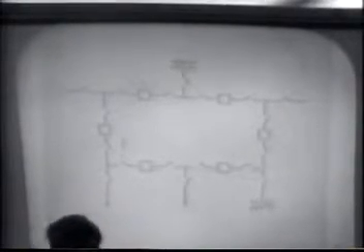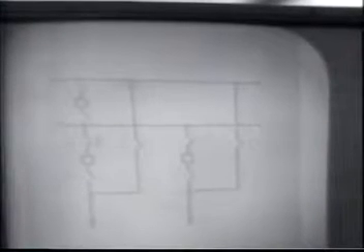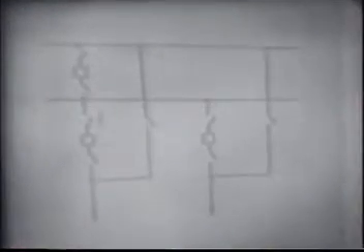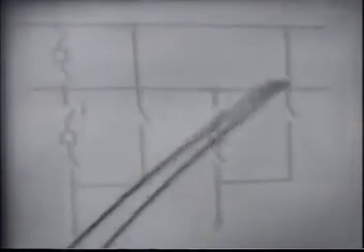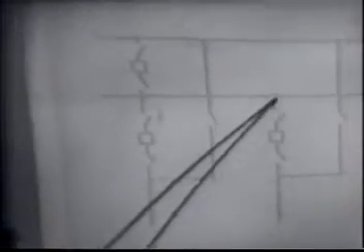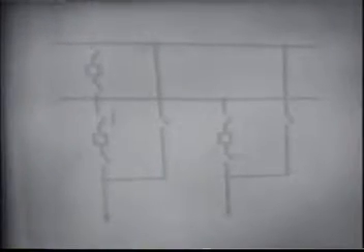The next, on sketch number 5, goes a step further. This would be the main and transfer bus arrangement. You have here the main bus, connected directly to the main bus, a circuit breaker feeding a particular line. We've shown two lines in this particular station. So it starts out in the same general configuration as your single breaker, single bus system.